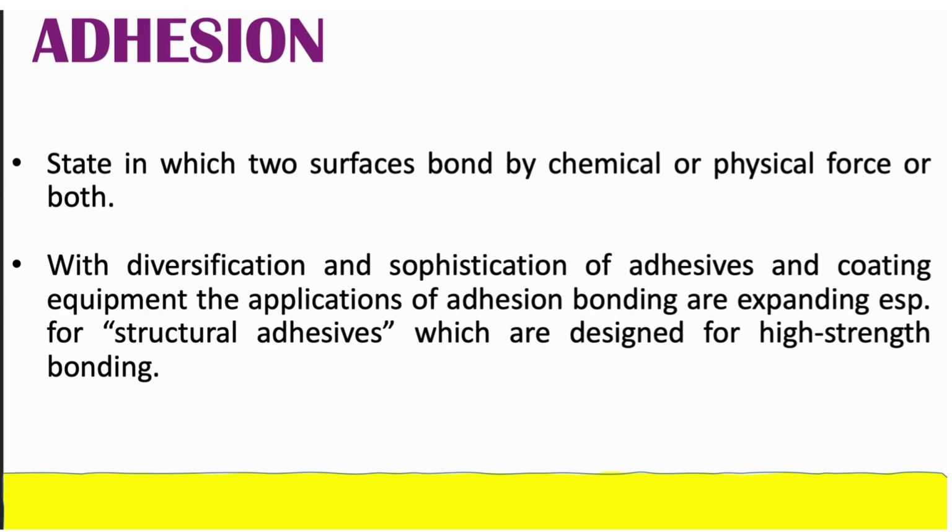So using a coating with these adhesive properties of structural adhesive, which is basically high strength bonding, provides area bonding, resulting in a lightweight and stronger bond at the same time with, of course, a very small amount of adhesive used. Combining area bonding with point bonding, such as spot welding, rivets or bolts, a bond with even higher rigidity can be created. For example, bonding which uses spot welding in car body assembly processes. So that is the story, the background of adhesion and adhesives.